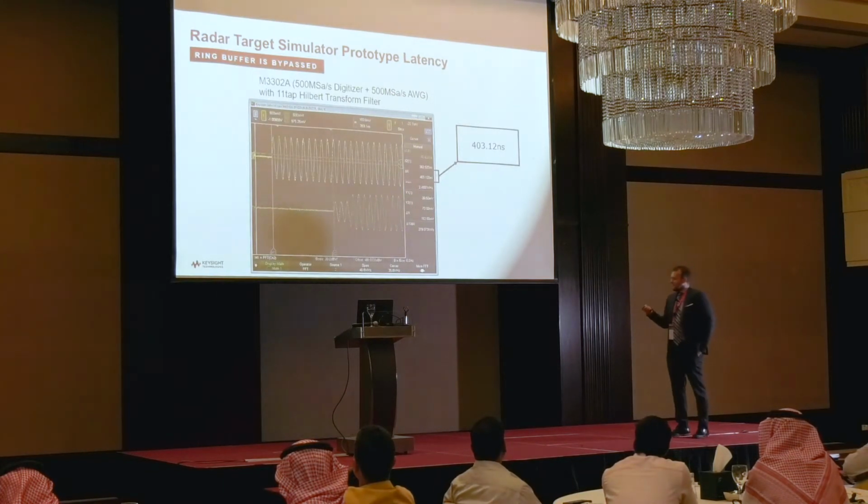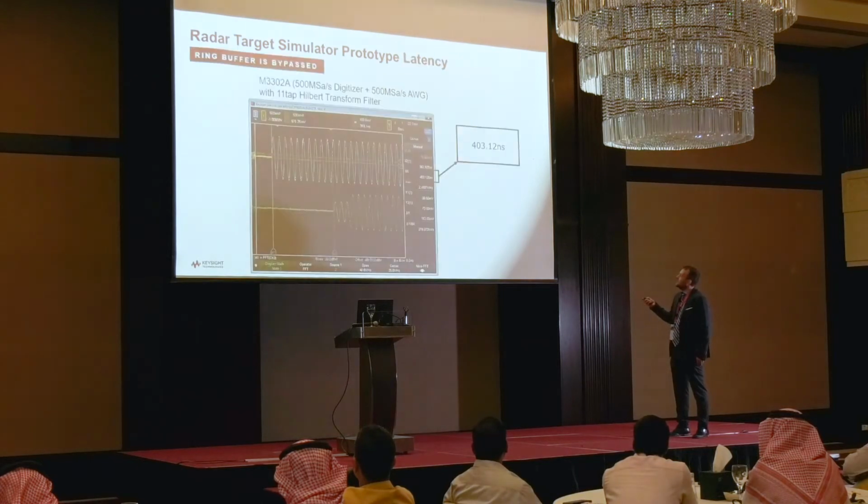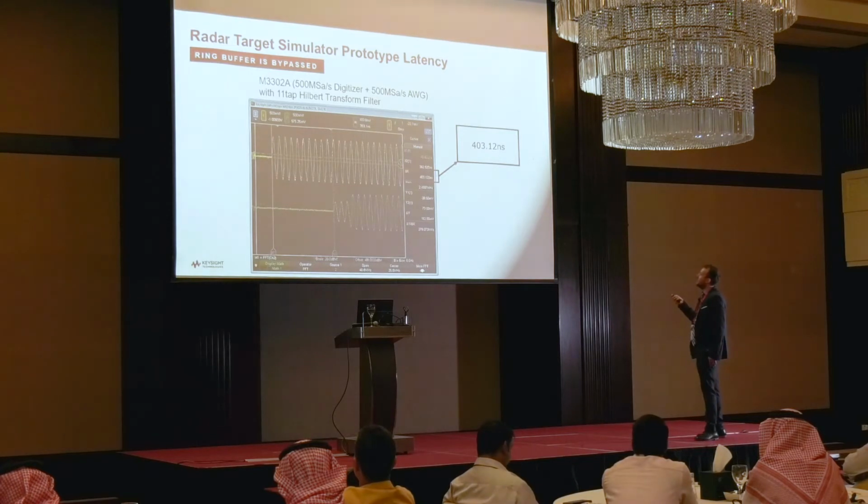So I mentioned latency in the past, and the latency really is the time between the input pulse being captured and a new pulse being generated. What we see with this system, as I say, it's quite simple in its capabilities, but we have a minimum latency of just around 400 nanoseconds.